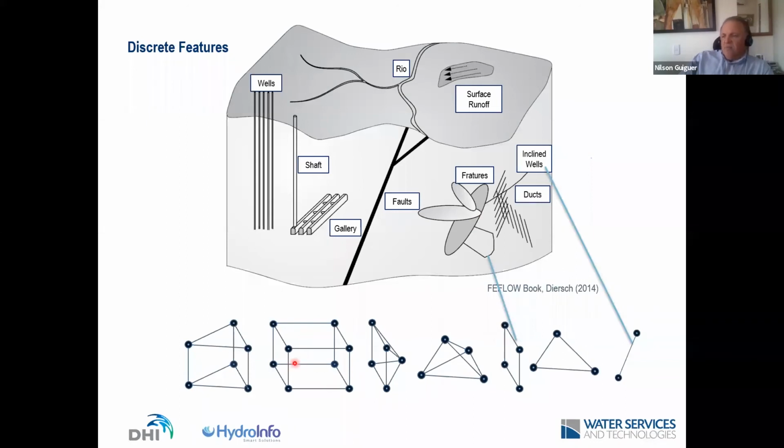And you can also mix, for example, most of your model you represent with prismatic elements, because it's still easier to work in the interface with layered models than with a totally unstructured model. So a good strategy is to represent everything with prismatic elements, but close to where you have an inclined fault you want to represent, you change to tetrahedral, so you can mix and match.